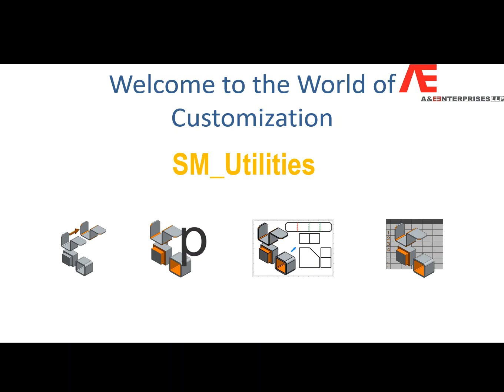Once you do that, you also have to export the flat pattern at 1:1 scale, in DXF or DWG format, which can then be given for laser cutting.